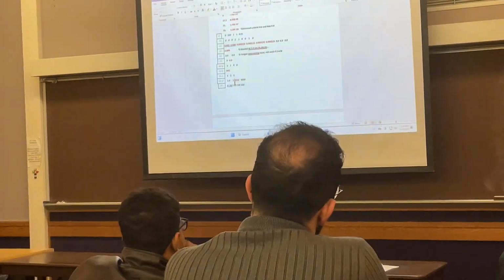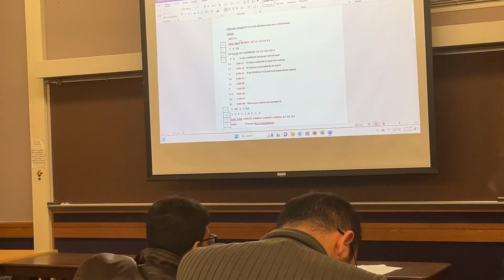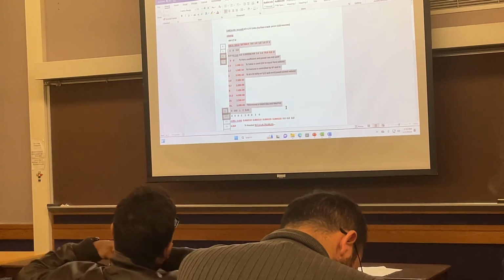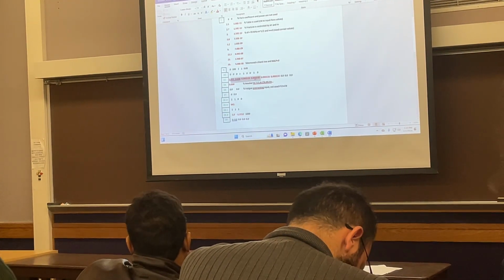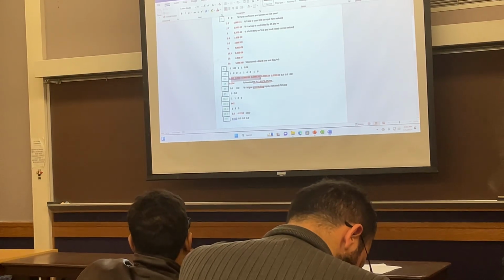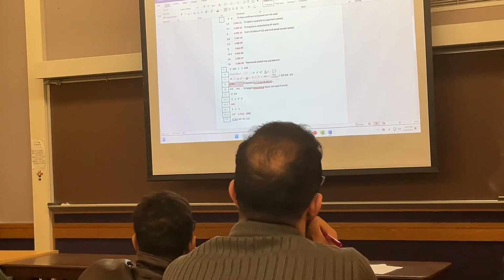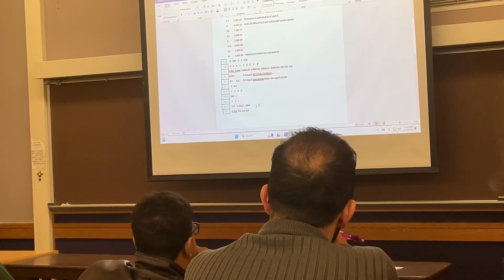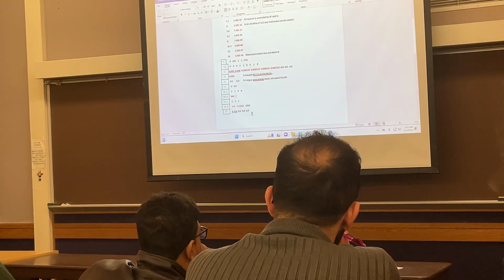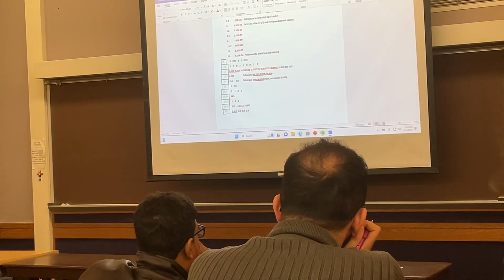So for your case, other than the material property, which is the same for both specimens, from here to here will be the same for both specimens. What you need to define is the width, thickness, initial crack size, and final length of the crack, and the stress level. So this is just one file for calculating the fatigue life for this stress level and those cracks. So you can have multiple of these in a single input file.